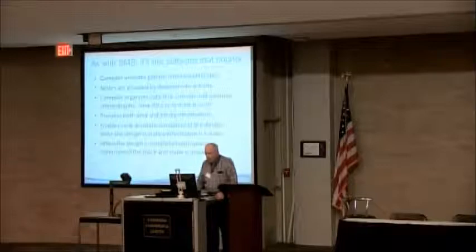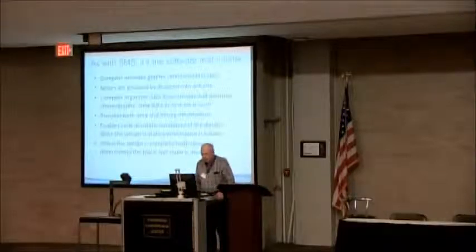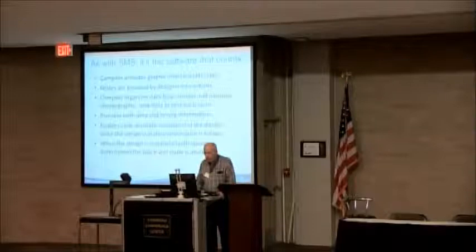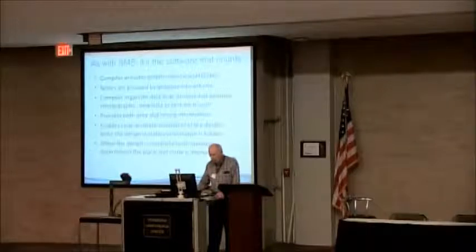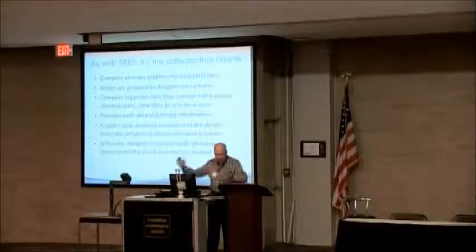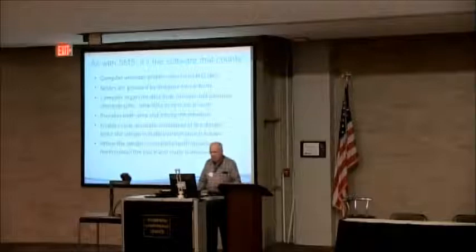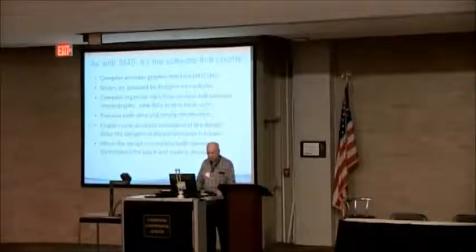So, as with SMS, it's the software that counts. The compiler provides the graphic interface, ALD-like. Nodes are grouped by the designer interactions, and the compiler organizes data flow streams and memory choreography. This is very important because we have a static flow of a pipeline, so the memory, we have 6 channels of memory, and they have to provide new data every single cycle to all the pins. There's no such thing as having a miss.